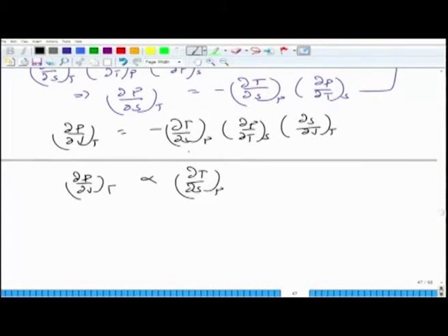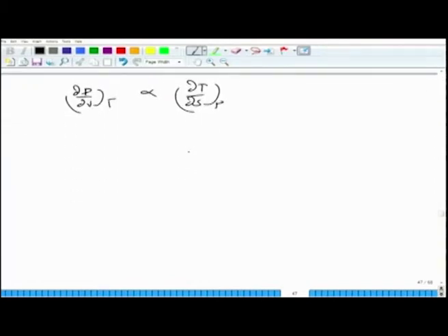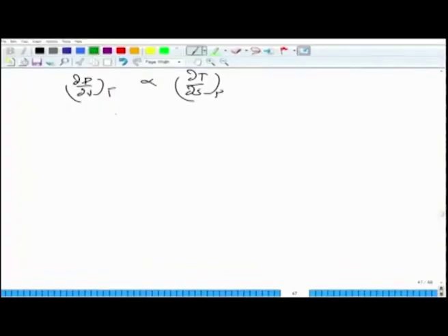Okay. Now these criteria are quite important also. So I will just make use of these criteria for understanding the criticality also, and then we will stop this lecture. So let us take a case of a vapor liquid two phase system, or vapor liquid phase diagram on a PV diagram. Okay. So this is our binodal, or this is basically the saturation vapor and liquid lines. Okay. I can draw the isotherms. Okay.